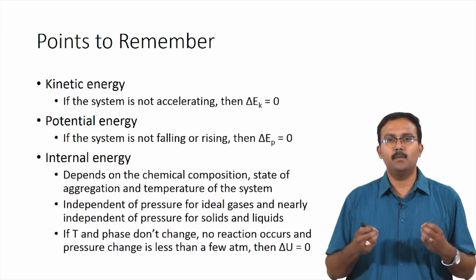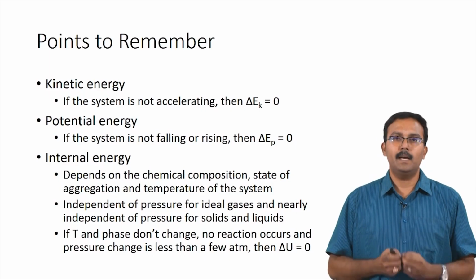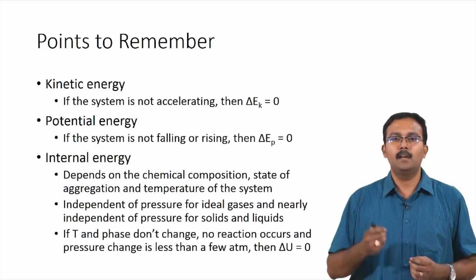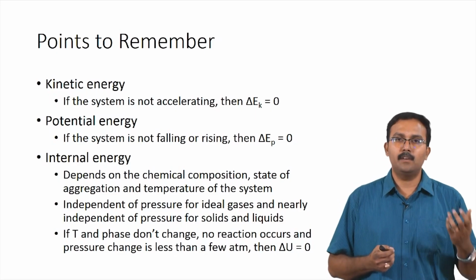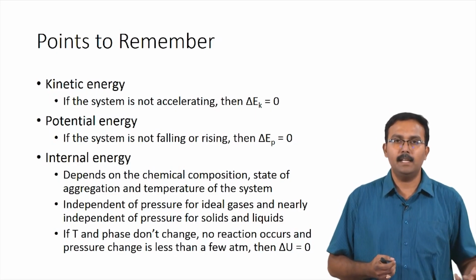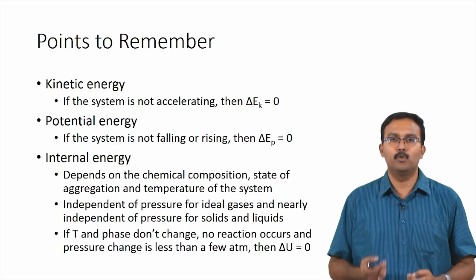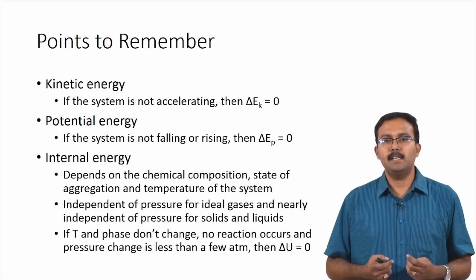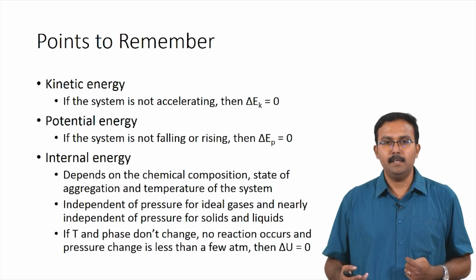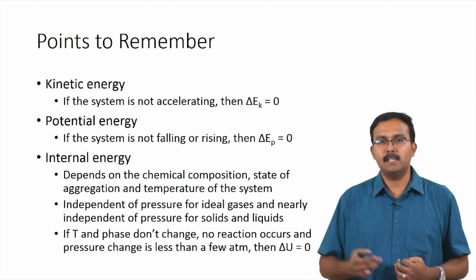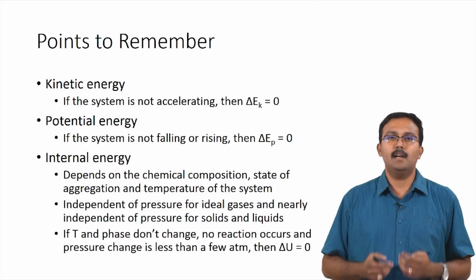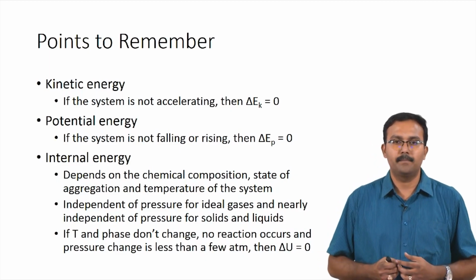So, by this what I mean is, whenever we have a process where only pressure is changing, then we can ignore the effect of change in internal energy for ideal gases and solids and liquids for the most part. If temperature and phase change do not happen, then you would have to assume delta U equals 0, or change in internal energy is 0, as long as reactions are also not happening.